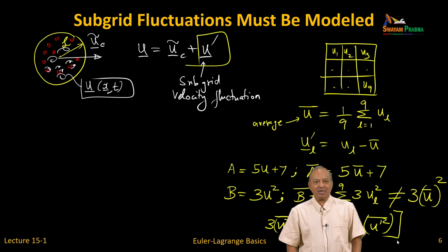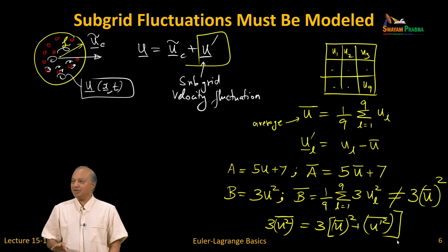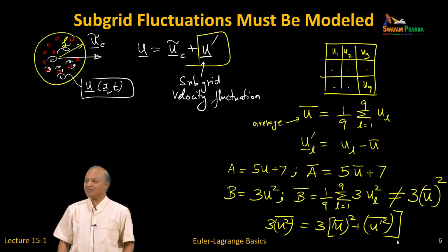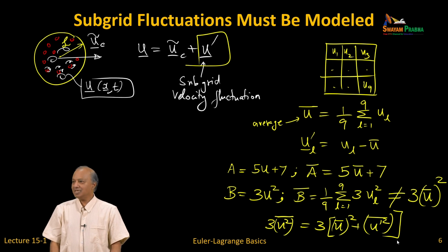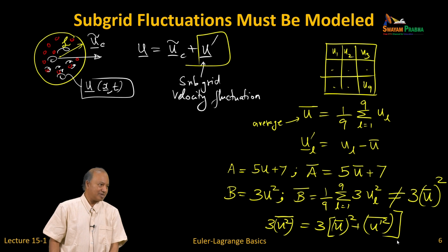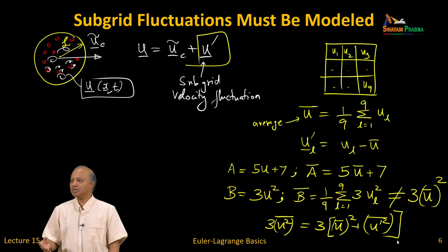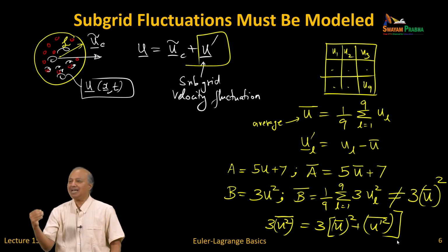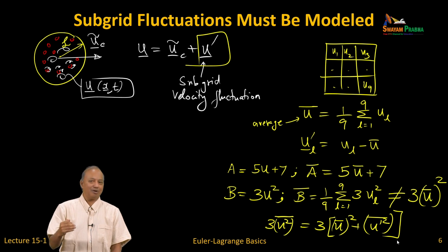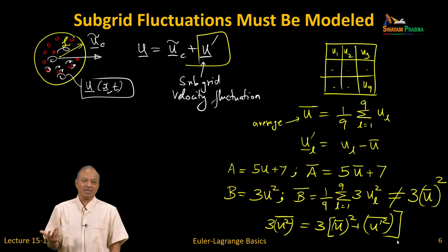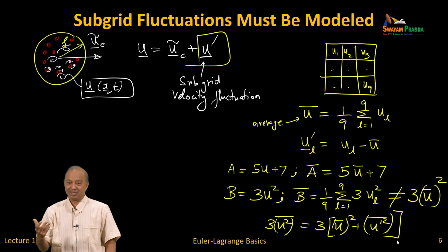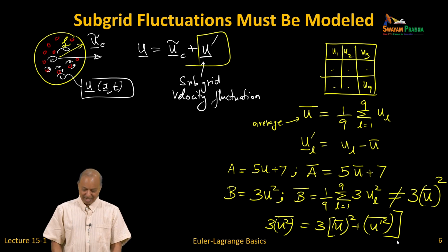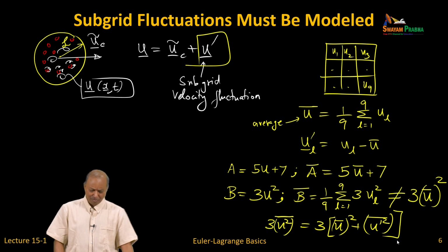The other set of models pertains only to the fluid. Now, you are saying, okay, there is a cell average velocity, but there is fluctuation in fluid velocity inside the cell. This is what typically is called Reynolds stress. Reynolds stress in the temperature equation, the average of U times T will be replaced by U average times T average. Every quadratic term, the average of a quadratic term is not available. So, you will have to write that as a quadratic term of averages, because we are computing only averages. So I tried to explain what that means.